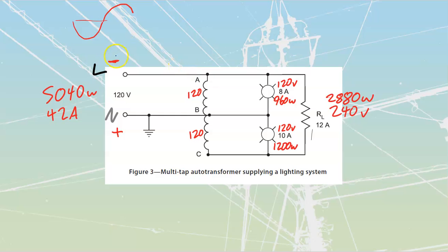Okay, let's go and drop polarity onto everything that we do know about. The things that we do know about is that this is going to have to be more negative, therefore this is going to have to be more negative, therefore this is going to have to be more negative. And if I have got negatives over there, are these sources or loads, do they have the option to be a load? They don't have any option. They are going to be loads.